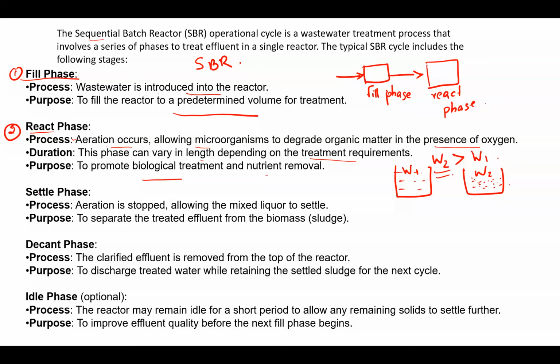Okay, then the third phase, which is the settle phase. Fill phase is filling, react means reacting. Then the settle phase: aeration is stopped, allowing the mixed liquor to settle. So the degraded material will settle down. Now the aeration is stopped. So next is the settling phase.